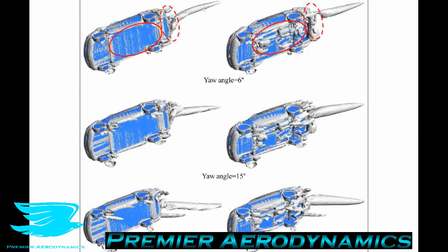So wherever we see these white tubes, that indicates that we have vorticity forming. Oh, sorry, vortices are there. Not just vorticity, but vortices. And figure B shows that there's a lot more vorticity coming off of Model B's underbody, as expected. And the vortices downstream of Model B seem to be much more plentiful and larger than Model A.